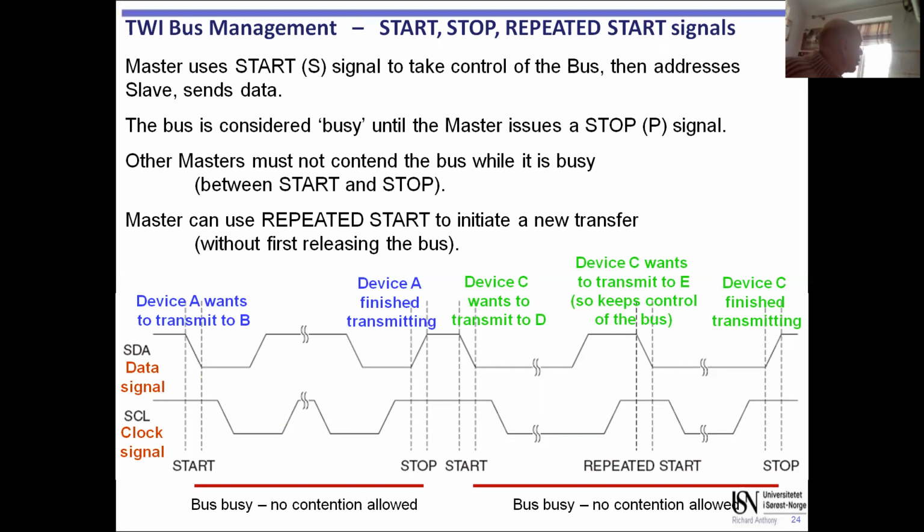And when the clock signal is high and the data signal goes low, that combination means transmission is about to begin. This is the I want to transmit signal, and then the clock signal is continuous. This actual diagram is from the manual, but you can imagine that there would be lots of clock pulses. This is just a cutoff, and you would transmit your data. The device that's transmitting can choose when it wants to stop transmitting. So to stop transmitting, the data line goes high while the clock signal is high. That is a signal to say stop transmitting.